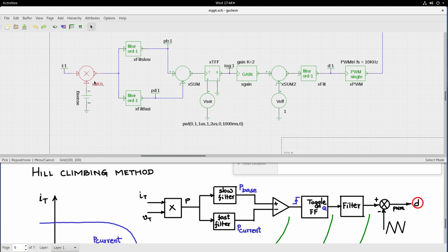This multiplier block is a new block. You see that NgSpice integrates very nicely with CEDAR tools, and CEDAR libraries are also integrated well within NgSpice. These set of blocks here are analog behavioral modeling blocks, and they are obtained from the NgSpice library.